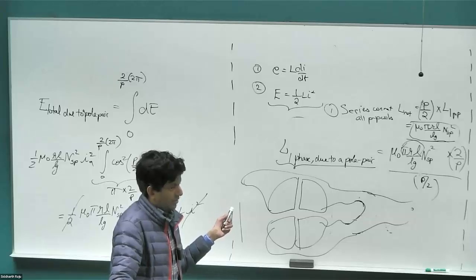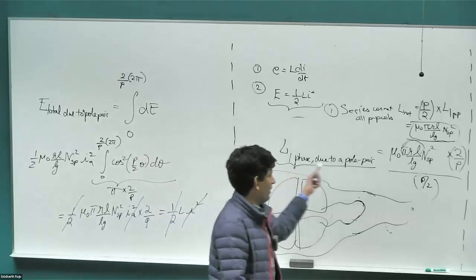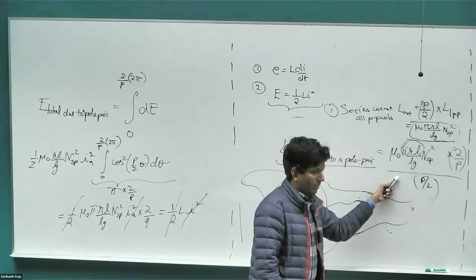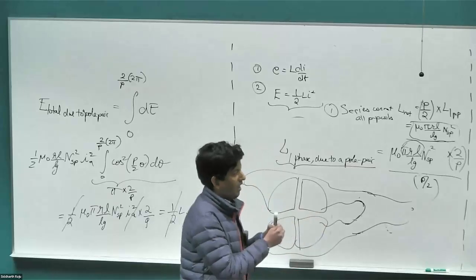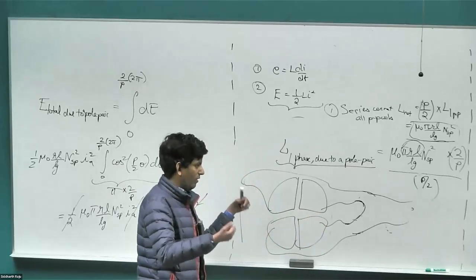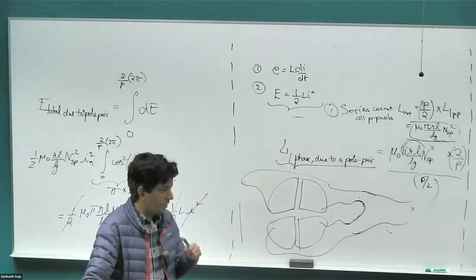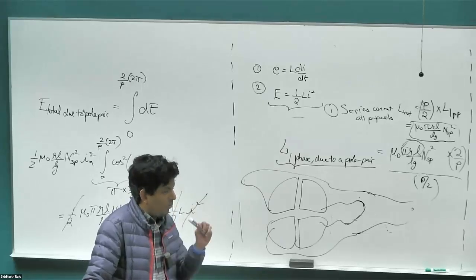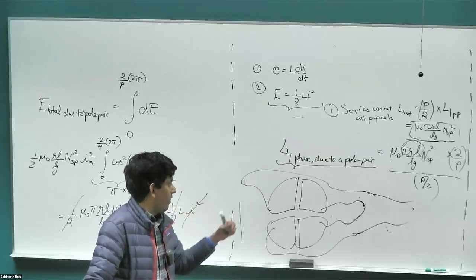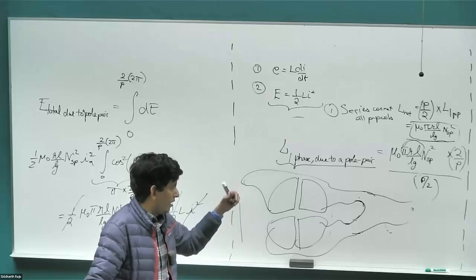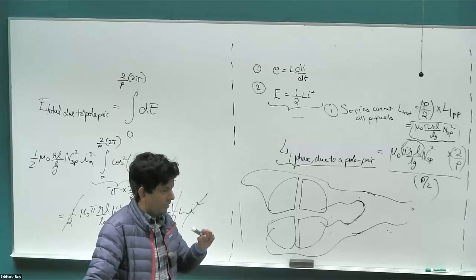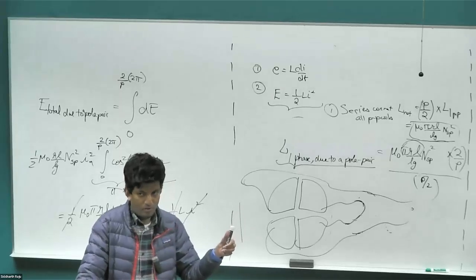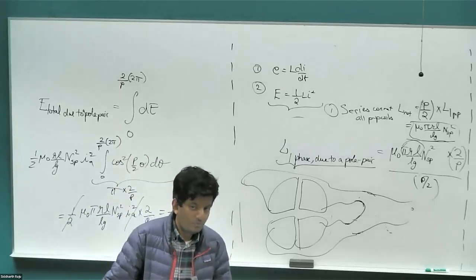Oh, okay. Right? Because if you split them in parallel, basically the inductance is much lower. So when you put a voltage across, the current can be quite large. Right? And the large current can split across multiple coils and then create whatever torque you need. So if you want a motor that needs to take a lot of current, then you would put the windings in parallel so that the current can split across multiple coils and then you have manageable currents across each of those coils. What would be the complementary pair of it? Yeah, okay. On a small current, but you still want to use all the coils.